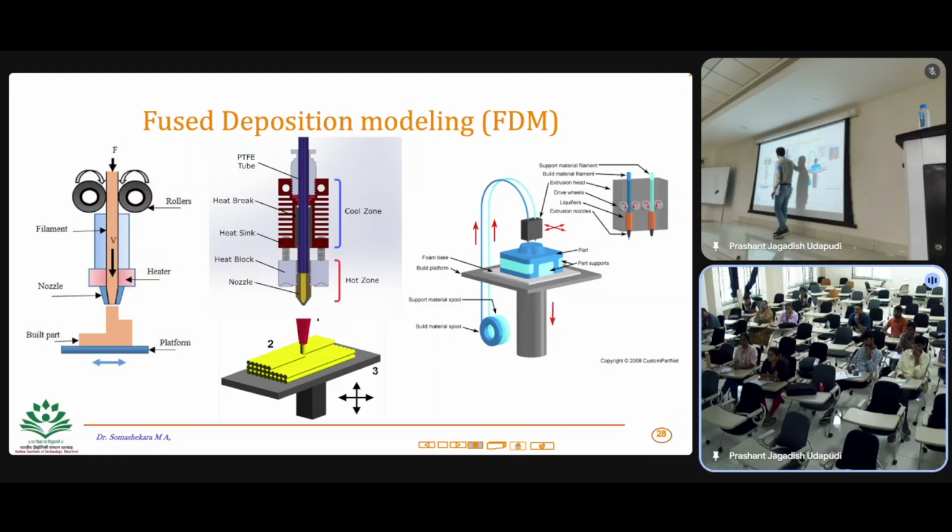But before that, you have the heating area, because as soon as the solid filament comes inside, you need to melt it, right? Initially, it has the standard filament size, 1.75 mm. But your nozzle is not like that, and if you try to print without heating it up, it will not work, because you cannot bond the layers, or you cannot bind them together. So you need to make sure the material is heated above its melting point, and then you make it semi-liquid or semi-solid.